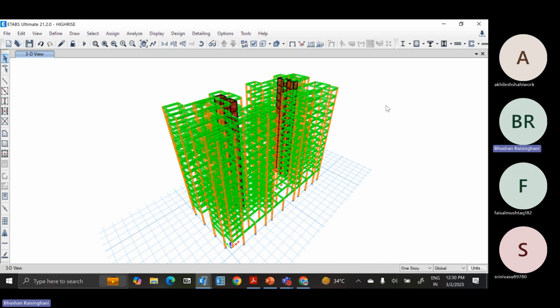And the design for this building, if it is similar to the other building, then no need to model this building. So if everything of building 1 is the same as building 2, then no need to model two buildings. If there is a difference in the geometry or the properties or the sizes, then you have to model both buildings. Otherwise, you model one building with podium, and if this building is separate, then you create another model in which this building and podium is there. Take the worst case. Then you create a common multi-building with podium model for overall stability check for submission to the authorities.